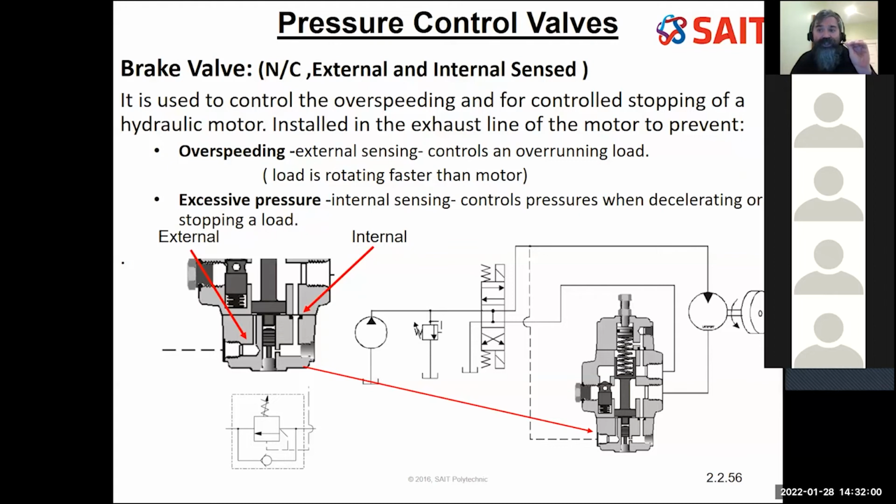I don't want to have a sudden stop, boom, that might cause a pressure spike and cause some damage. It might cause the person who fell in to get injured. I want to stop fairly quickly, but in a controlled manner, like braking a car. It's better to brake a car under the brakes than crash into a wall and come to a stop real quick that way. So we're going to do that with this valve.